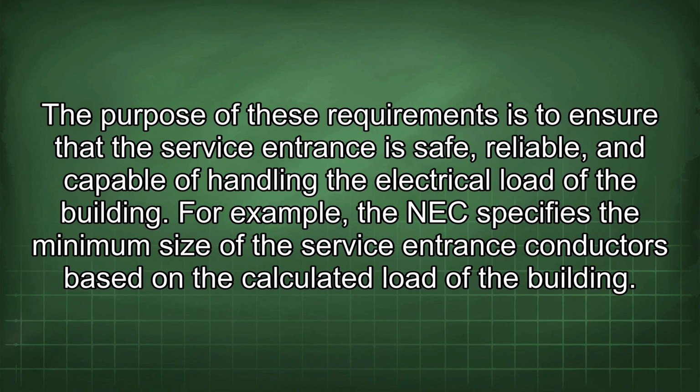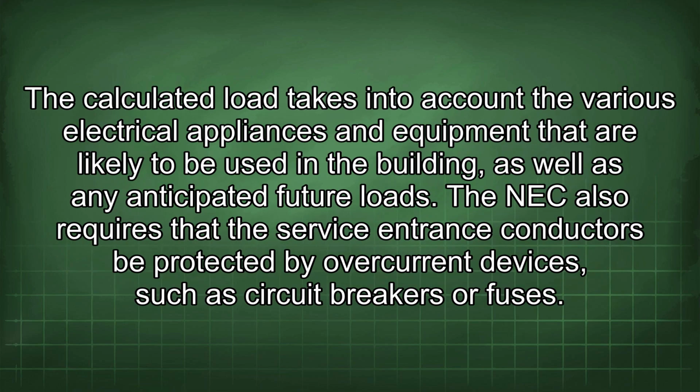For example, the NEC specifies the minimum size of the service entrance conductors based on the calculated load of the building. The calculated load takes into account the various electrical appliances and equipment that are likely to be used in a building, as well as any anticipated future loads.